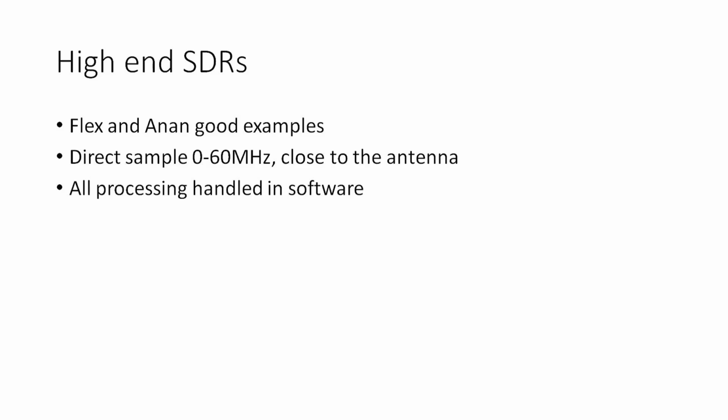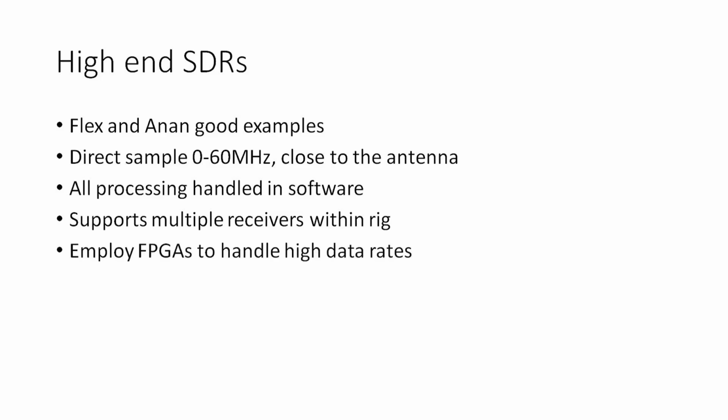All the processing is handled in software, and they support multiple receiver slices within the rig. They use FPGAs to handle all that data, and then they put out fairly low rates over Ethernet or USB.